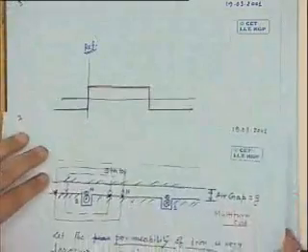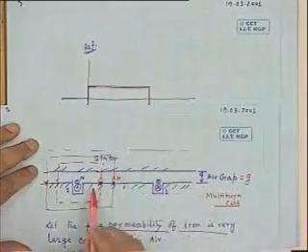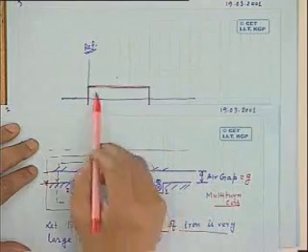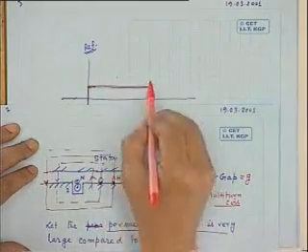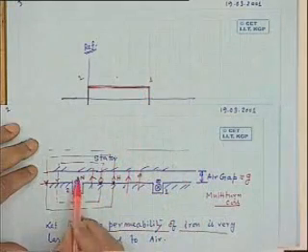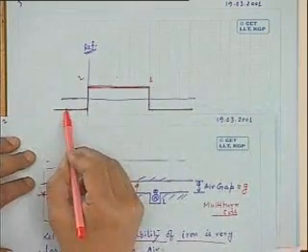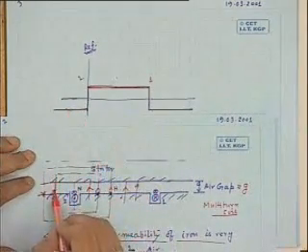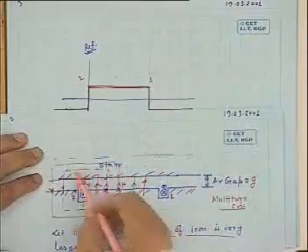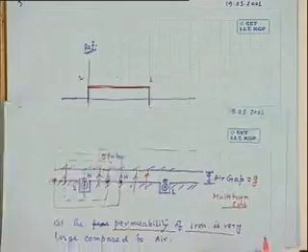That is, from this to this is this to this. Here all the lines of force will be upwards. And suppose I have assigned a positive sign to that. So till slot number 1 is reached, it will remain constant here. But the moment you cross this central line and come here, it will become negative. The MMF direction is from top to bottom. That is, if you assign this to be north, this should be south. That's all. Mathematically we represent it like this.